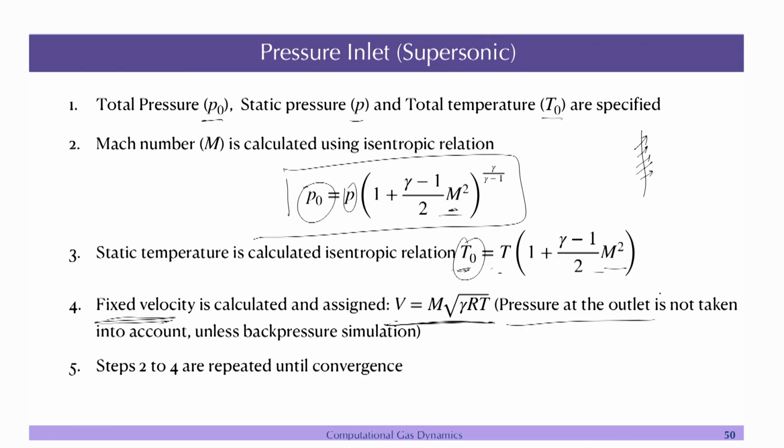And one thing to note here is that, because there is no reflection from inside to outside, that is allowed, that you can specify both the pressure and the velocity, but in the subsonic flow or the incompressible flow you cannot do that. And you cannot specify anything at the boundary, because all are right running, so it will go out. So, everything will be extrapolated from the interior.